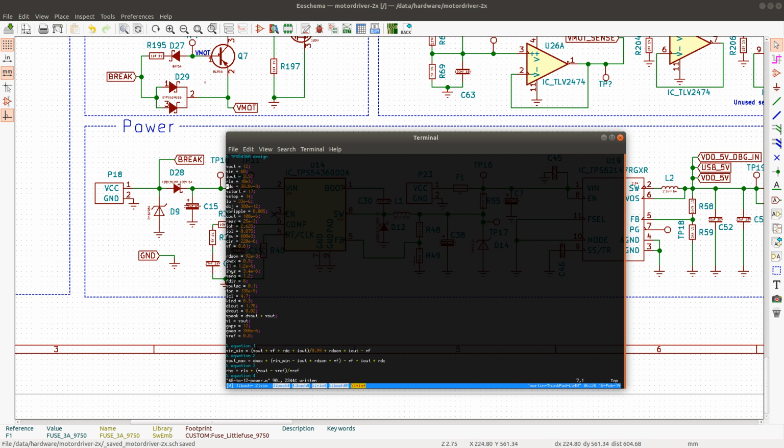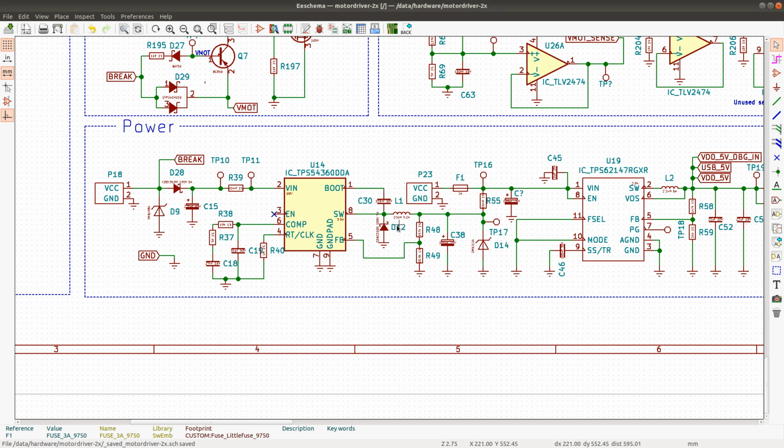Now, this is the DC resistance of the coil, and it's specified in the data sheet of the coil that I chose. I had to update this coil from the previous component that I used in the previous video, because that component had a much too low current rating, and for some reason I missed that detail. So I had to replace it with a 33 microhenry higher current inductor. It has the same footprint though, so I didn't have to change that many things.